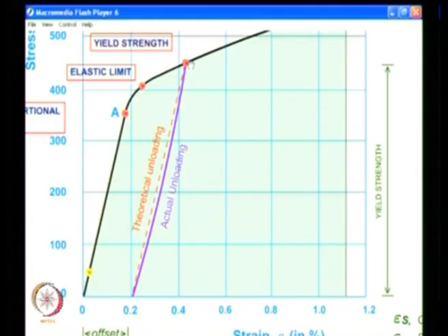So, what you find is, at 2000 microstrain, the material has yielded, but you permit that for you to find out what is the yield strength of the material when you are not able to accurately locate it in your stress strain curve. And many actual components, I have components interacting with one another, and I can't have large strain.